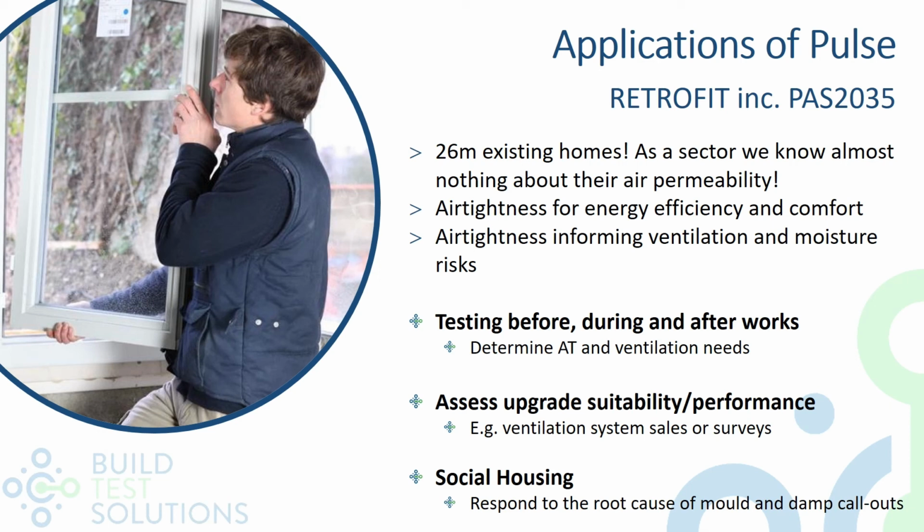There's also using Pulse as a means of assessing specific upgrade suitability, so whether you're looking at promoting and selling draught stripping or ventilation systems, Pulse can be a very informative measurement in that respect. And of course it's a tool in social housing for understanding the root cause of mould and damp issues. Again, understanding that ambient background ventilation rate and whether the root cause is occupant behaviours or indeed particularly airtight fabric with inadequate mechanical ventilation provision.